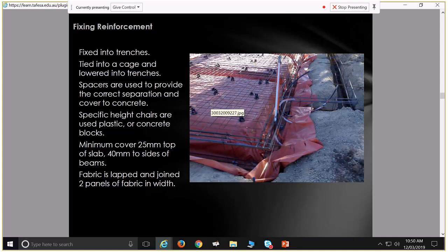Is that on the side where there's none of the plastic, is that just a strip footing section? Yeah, so that's external. Outside the building, you don't need to have plastic. You have to protect the inside of your building from moisture ingress, but outside you don't. So that strip footing might be for a veranda or something. Yeah, a deck, something like that.